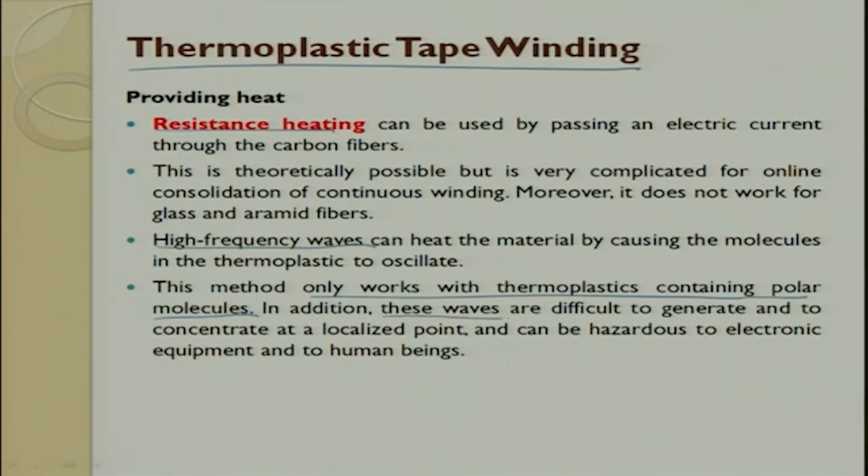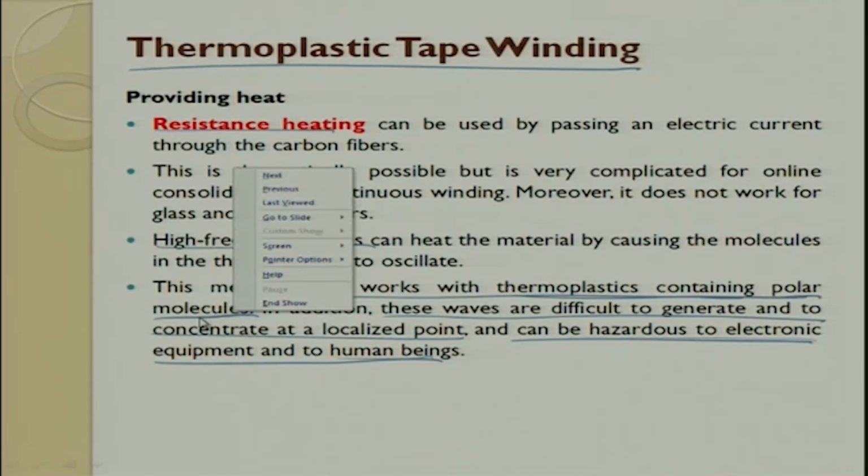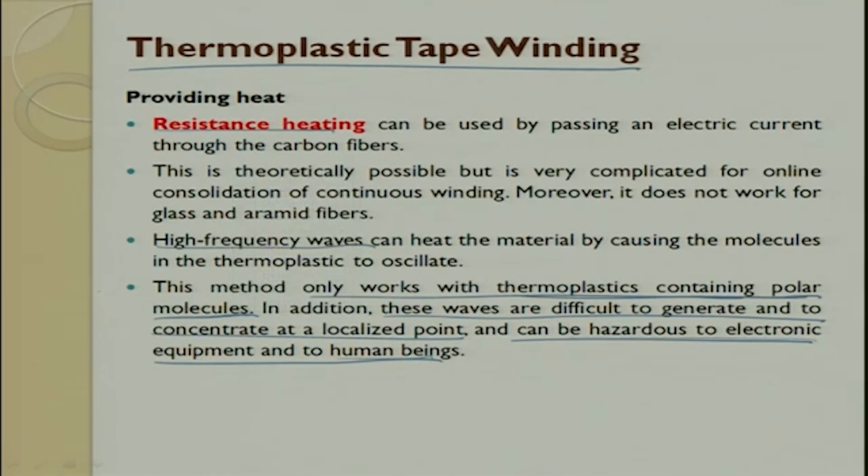In addition, these waves are difficult to generate and to concentrate at a local point, and the electronic equipment can be hazardous to human beings. So, thermoplastics containing polar molecules, this is very important. If you have polar molecules only, then only high frequency will work. It is something like your microwave, with polar molecules, that is what we are trying to say.